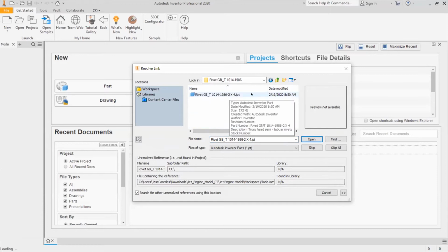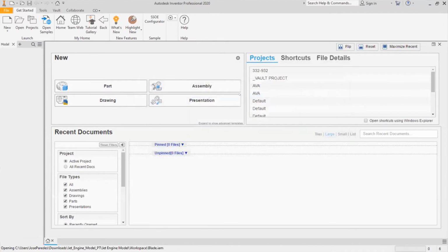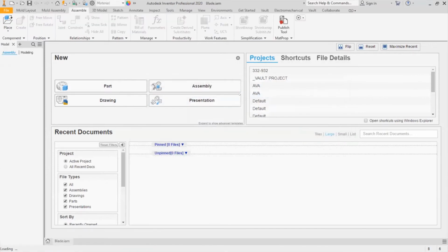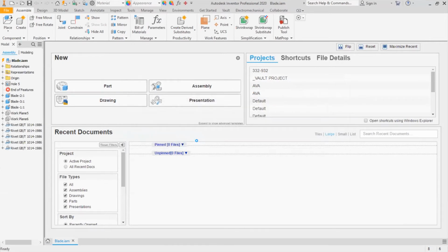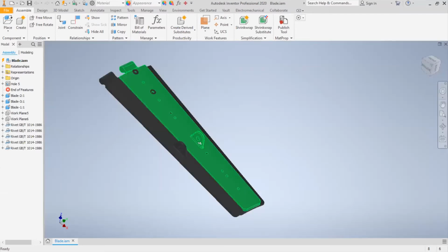And then again, it's named exactly the same. So once we resolve this link, we should be good to data load in here. Again, before doing that scan, the easiest way to know whether or not you have some clean data here is to open up the assemblies you're trying to load. If you run into errors like that one where, hey, I'm missing files, you'll know you're going to run into those errors during the scan as well.